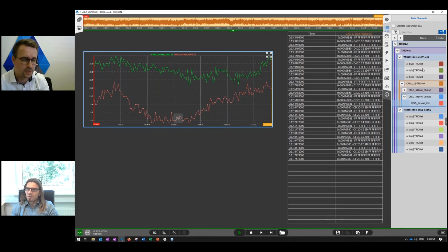Perfect, perfect. So this helps so much because you don't lose any data anymore on the CAN bus, and it allows you to just log the CAN bus. And if you think that there might be information somewhere that you did not decode, you can decode it afterwards and synchronously to your measurement.